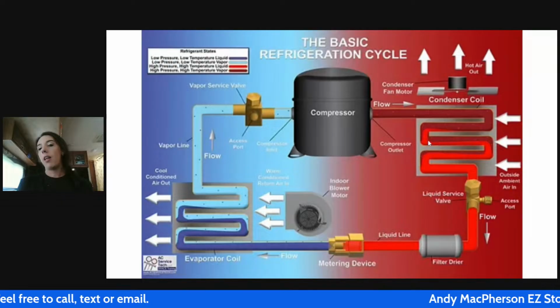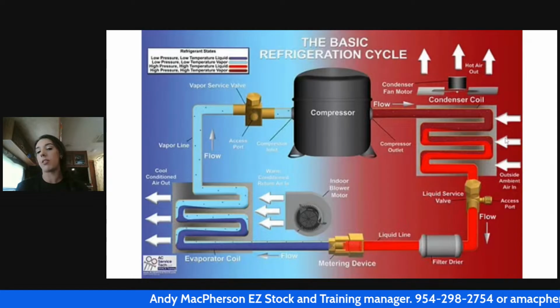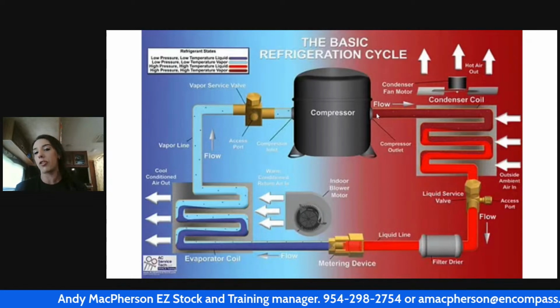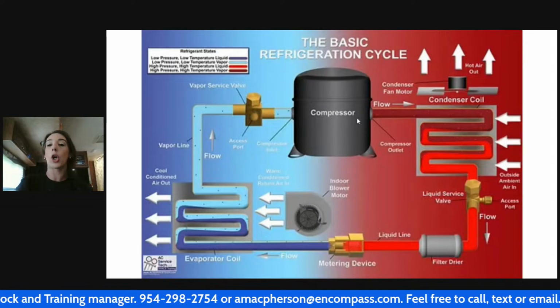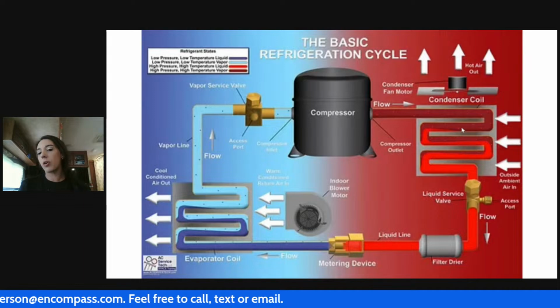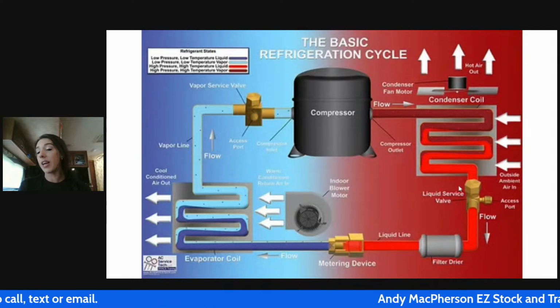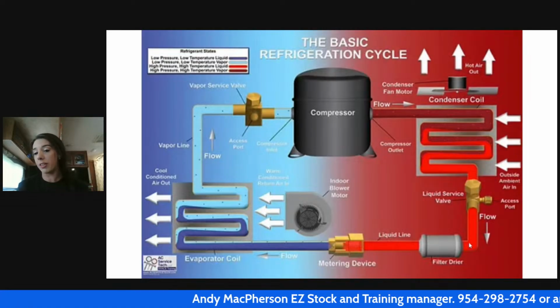Through our condenser coil, we can notice this phase change. The condenser coil isn't creating a phase change necessarily. That's the compressor's job. The compressor's job is to make sure that a phase change can occur. Once we get to the condenser coil, halfway up this coil, we're going from mostly vapor to mostly liquid. And by the time we're exiting that condenser coil, we are 100% liquid.